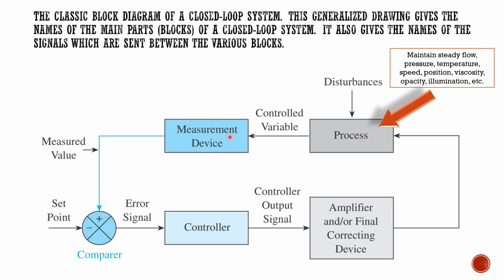So I've got something that measures my light. I compare it to where I want it to be, and if there's a difference, either it's too light or too dark, I make a correction. My controller is going to add dye, or however you color glass, and hopefully that'll make the correction. And then if where I set it and where it actually is are the same, the correction signal will be 0, so that error signal does nothing to the controllers to change the process.